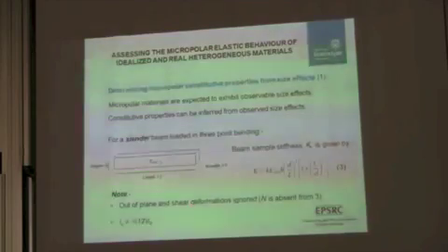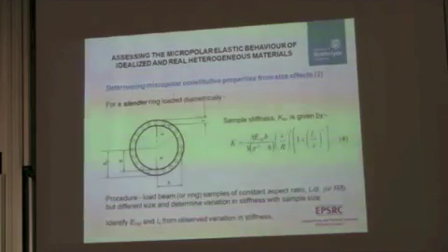As I've already said, in this slender beam case we ignore out-of-plane deformation, and we assume that the shear deformation is negligible. Hence, the coupling number is absent from this equation. Also, in everything I talk about, the length scale parameter that we use is actually a factor of root 12 times what people use as the conventional length scale parameter.